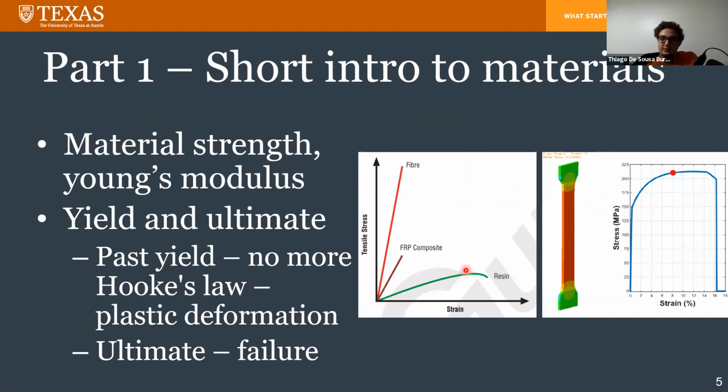Actually, if you have taken materials lab, or if you will take materials lab, when you get to test high density polyethylene, basically cutting board material, you put it on the tensile test and you start stretching it. If you stretch it really fast, it breaks really easily. But if you do it slowly, I think our sample started at like 50 millimeters and ended with like 500 millimeters. It just keeps stretching out and doesn't break.